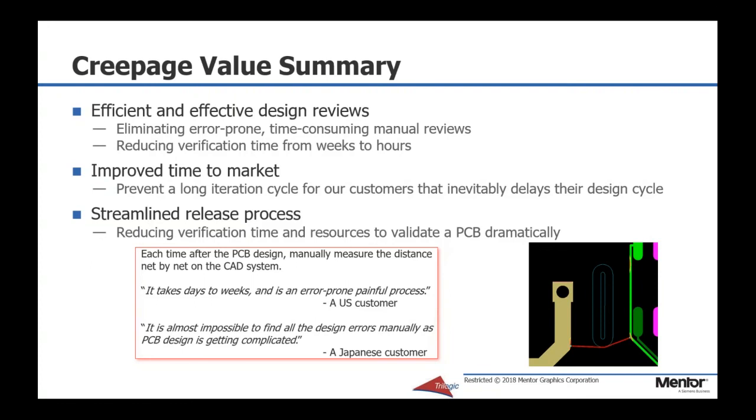And when you take into account the electrical perspective these DRCs provide, they are not just basic DRCs. They have the ability to assign IBIS models and take into account other electrical factors. Here, in the case of the electrostatic discharge and high voltage safety element in creepage checks, for example.